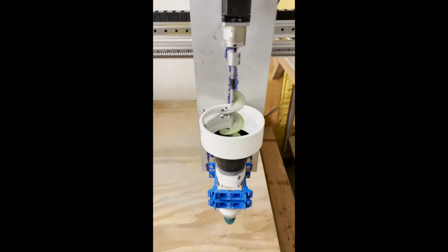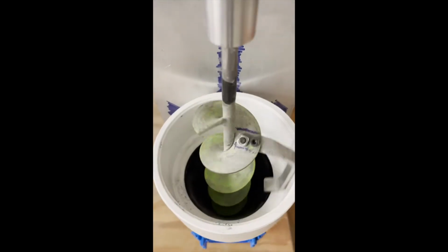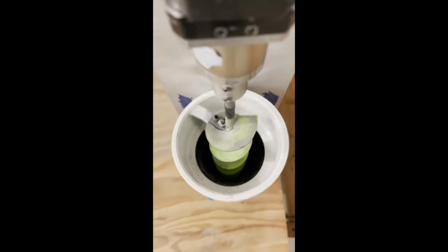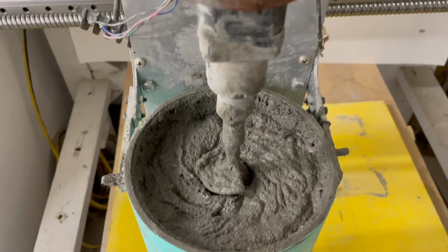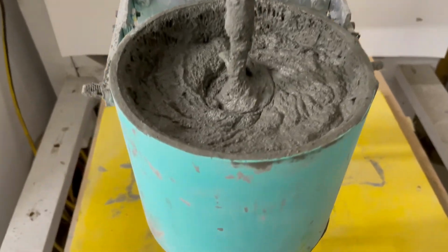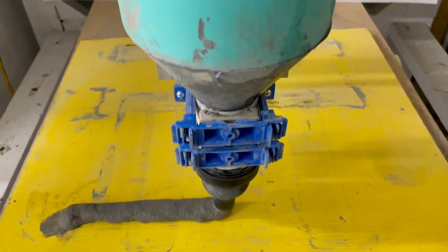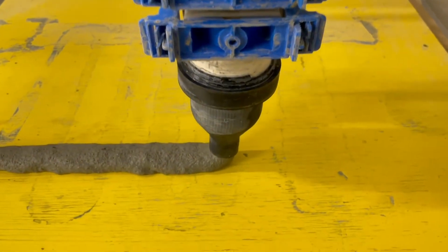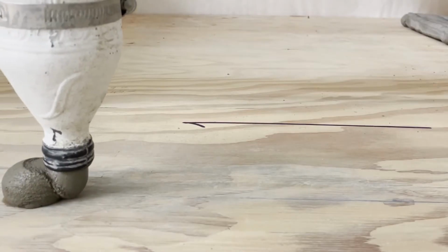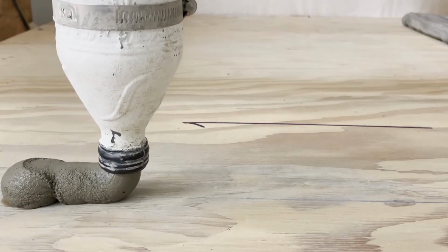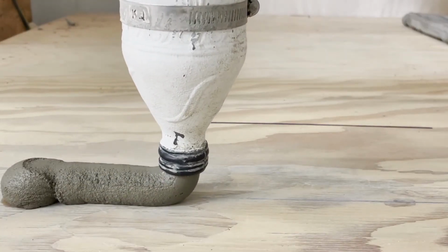Extrusion is the key step in 3D printing of concrete materials. Extrudability is a property that shows how easy it is to extrude the material and push it through the nozzle. We can define extrudability as the ability of the material to flow continuously through a nozzle without any segregation. Also, to form a continuous filament without voids and discontinuity.